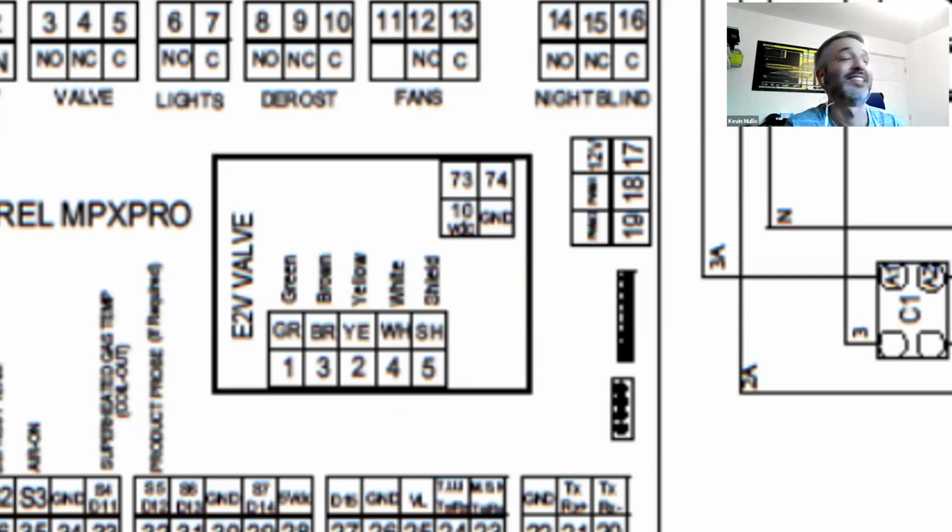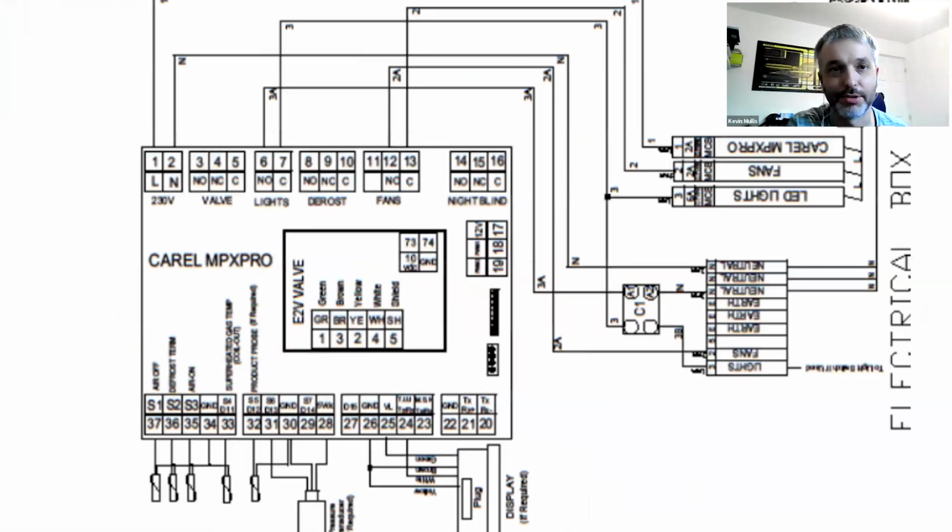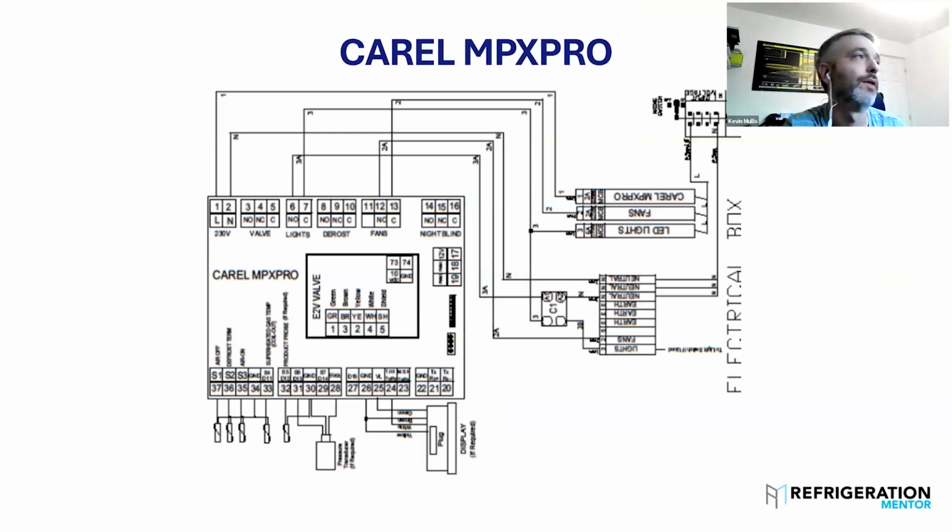It doesn't actually really matter exactly what that resistance is. It'll change a little bit depending on what the temperature of the coil is and everything else. But if you've got one that's, I think usually with Carel, it sits about 19 ohms. If you've got one that's 19 ohms and one that's 1,019 ohms, either your wire's broke or your coil is dead, I'm afraid to say. So, it won't work. What'll happen is it'll either drive open and never shut, or it'll drive shut and never open.